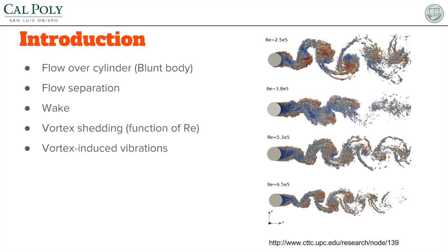The frequency of the vortex shedding is a function of the Reynolds number. Vortex shedding causes an uneven pressure distribution on the top or bottom of the cylinder. The alternation of aerodynamic forces induces vibrations, especially if the resonant frequency of the cylinder is met. This was the case when wind gusts caused Washington's Tacoma Narrows Bridge to collapse in 1940.